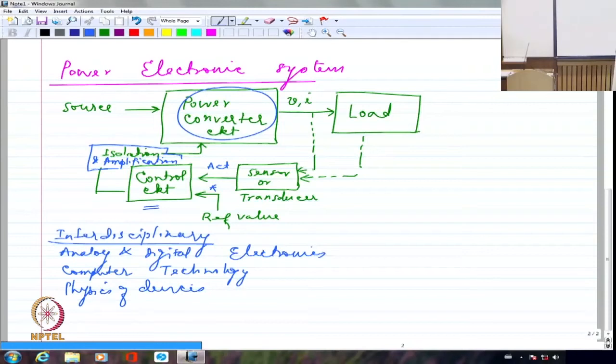The device, as it is, if I connect it to the circuit, will generate a lot of heat and it will conk out eventually. So to dissipate the heat, I put a black body attached to its body, and then the heat is transferred to the black body, which will radiate it. To increase the surface area, these legs are there.